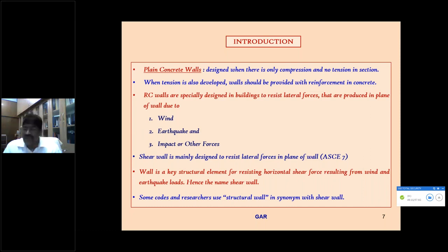So therefore, a huge shear force is acting. The elements which will resist the huge shear forces are all the structural walls. So they are called shear resisting walls, shear walls. So therefore the shear wall came in that way. The walls which will resist the lateral forces from the wind effects, earthquake forces, or blast load. But again, the same shear wall can be termed a structural wall. Most of the international codes simply define reinforced concrete wall or structural wall.